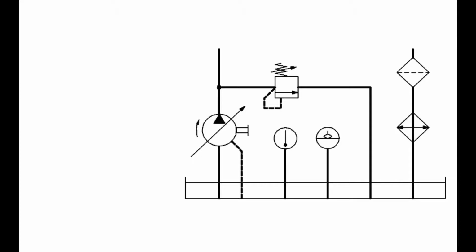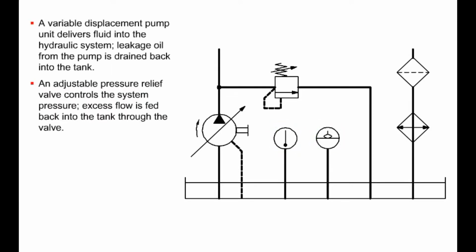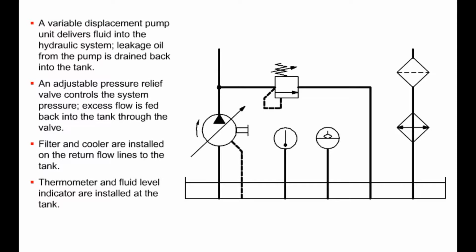Hydraulic fluid is heated up when flowing through a hydraulic system and picks up any contaminants in the circuit and carries them away. A filter is normally installed to purify the fluid and a cooler to lower its operating temperature. The fluid temperature in the tank can be monitored using a thermometer. A sight glass allows the fluid level to be continuously monitored.